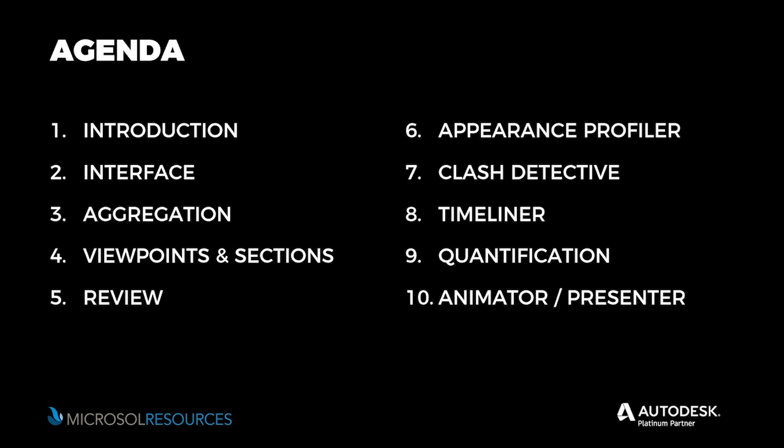The clash detective, probably the single most important aspect of Navisworks and the reason why most AEC professionals use the tool, which is a way to run clashes and understand where you may have issues between conflicting elements within a model. Timeliner, which enables us to essentially create a construction timeline via a schedule and the elements in the model.